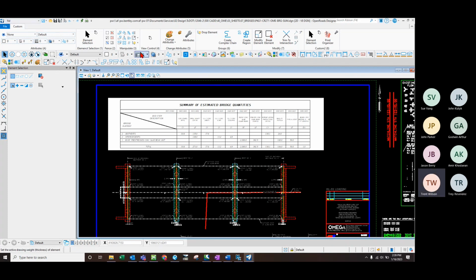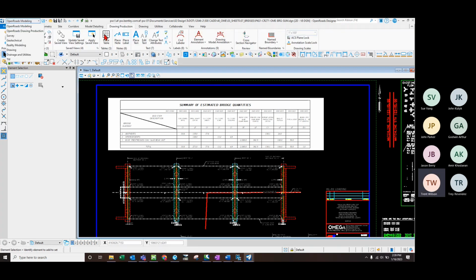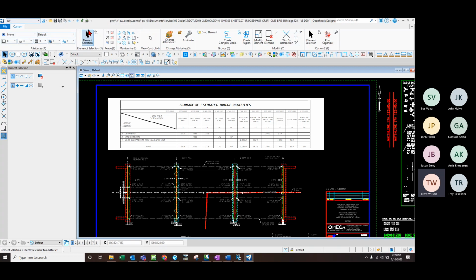And the way to get it like MicroStation is you can create your own ribbon tools. These are the ones that obviously come with it. For the OpenRoads modeling, I was testing and messing around with my own. I've set it up to where it's the same number inputs as it was in Geopack. So 5 will be change attributes and stuff. For me, that's definitely sped up my process instead of having to find the visual tool or find it in the right ribbon.